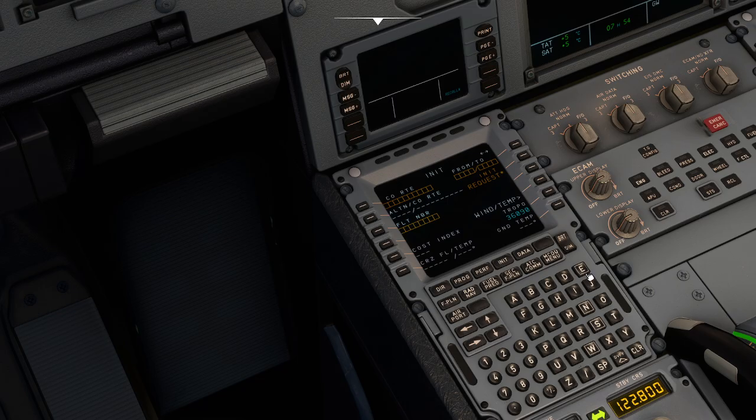Wherever it is from, EGLL, and it is to Brussels. Brussels is EBBR, and it is configured, and my aircraft is Sri Lankan 104 as filed in flight plan as well. So I'm putting it over here. That is also fine. And my cost index is 51.